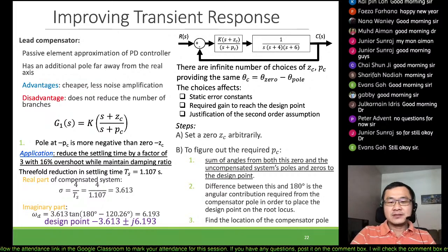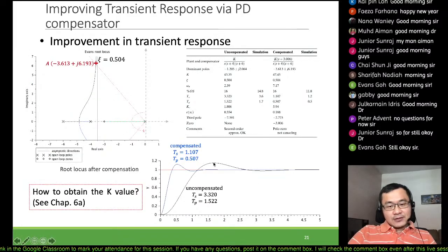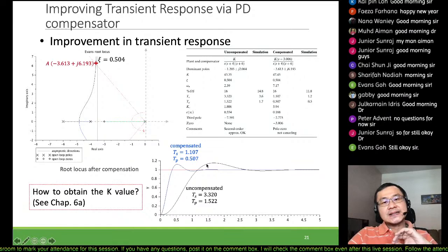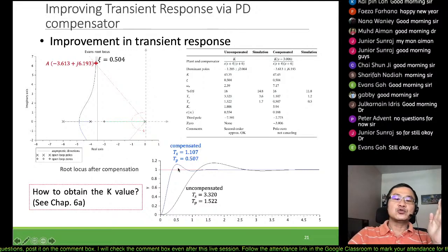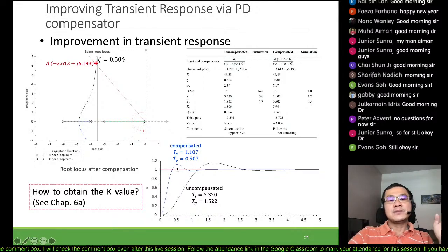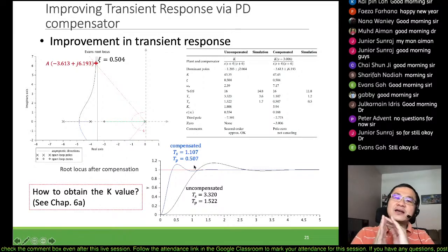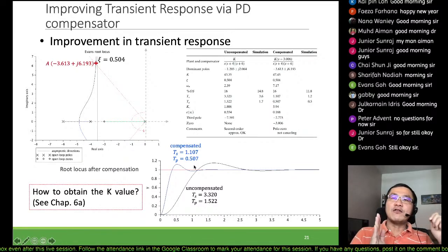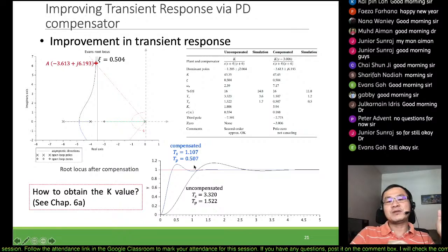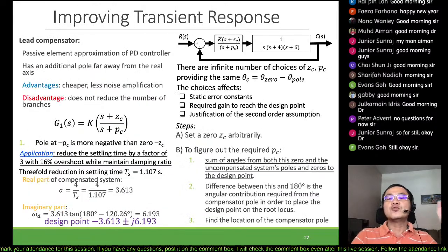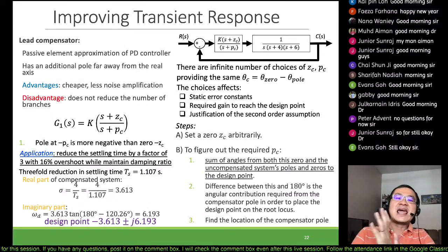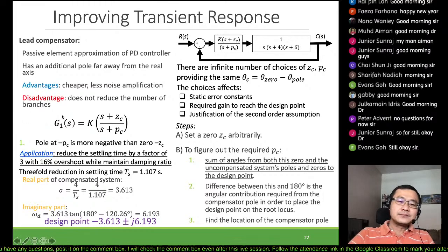Now remember, recall back, by putting this compensator, you have shifted the line forward, nearer to the earlier part, meaning to say you want to have a leading type of response. You lead it before your previous one. So we call it a lead compensator, whereas in the previous concept we wanted a lag compensator, right?